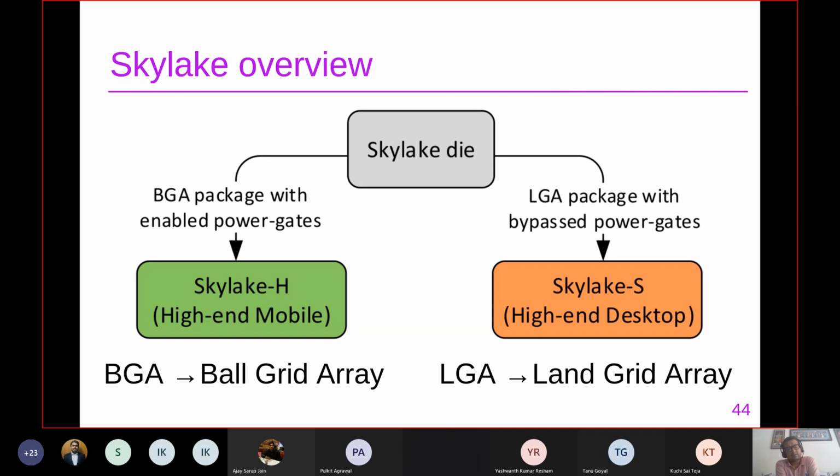In terms of microarchitecture, there will not be many differences. The only differences between these two will be the power circuits, or the power gating circuits. Other microarchitecture structures will be the same in both. You can imagine it like an Intel Core i5 in either a laptop or a desktop PC. The power management system and firmware decide that certain cores will allow frequency boosting and certain cores will not. These things will change, but otherwise the microarchitecture structure is the same.